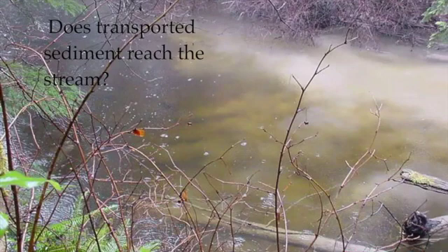If you have done a good job with road design, location, construction, and management, your equivalent clear-cut areas, or ECAs, and other indicators become largely irrelevant. 20 well-designed and managed stream crossings may have much less impact on a watershed than one badly designed and managed stream crossing.